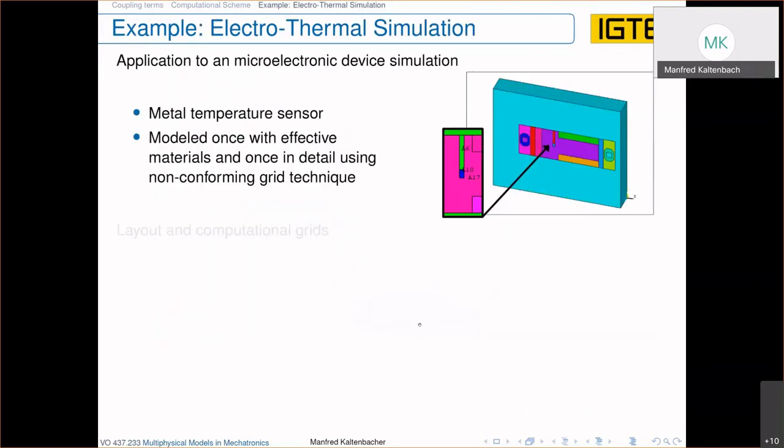Here I want to give you just a practical example that was a cooperation with Infineon Technology in Villach. As you know, mainly the death of a semiconductor, especially the power semiconductor, is due to mechanical stresses coming up due to strongly varying temperature fields, and as we just have seen here, these temperature fields are generated by the Joule's losses.